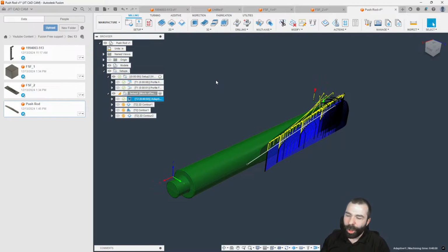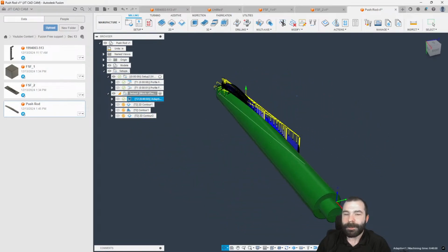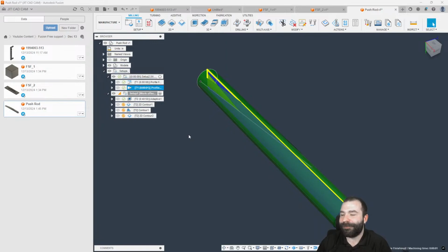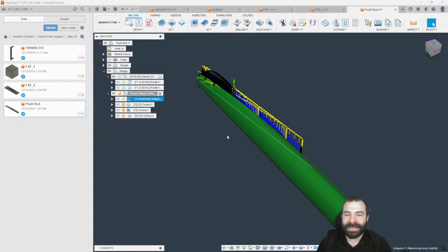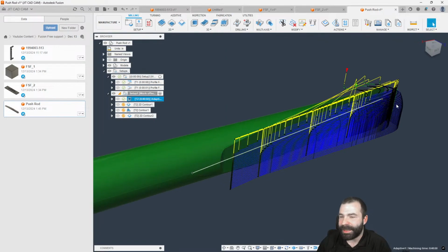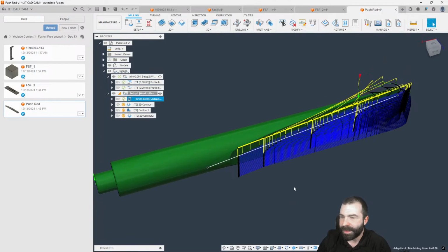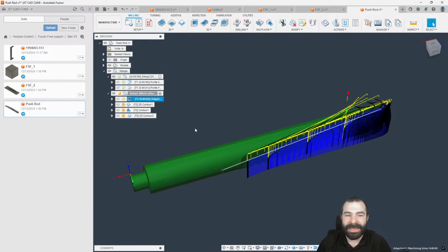So all that work, Deep Thinker, I know you were really fighting the system and trying to do a lot. But as you can see, had I just put a couple of lathe tool paths here to fake the system, the first thing my adaptive clearing has now recognized is where there is stock and where there isn't stock to be able to go in and machine things off. So this is, again, a night and day difference when you're simplifying and actually adopting the software more than most people think. Now, I do see this, again, if you have a manual guy on the lathe and he's going to turn the end of this part, this makes it way easier.